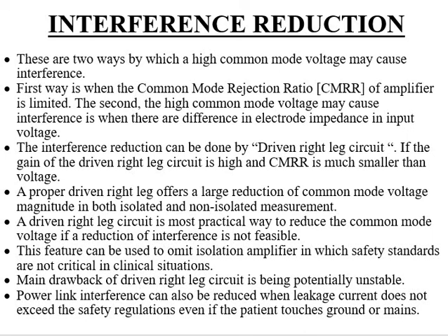That is why it is clearly discussed in the right leg driven ECG, with the right leg driven circuit and high CMRR. It is also discussed that this reduces the common mode voltage amplitude in both isolated and non-isolated measurement.